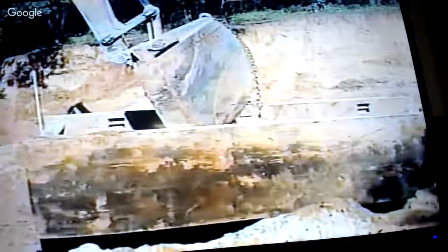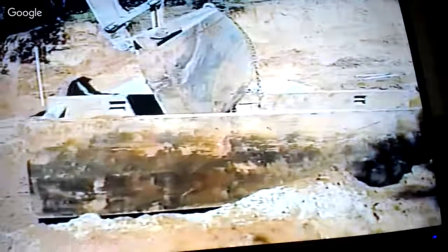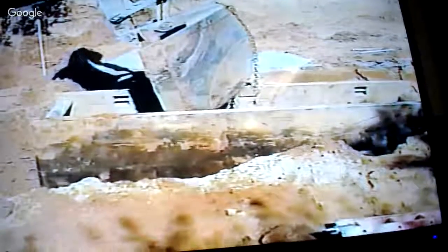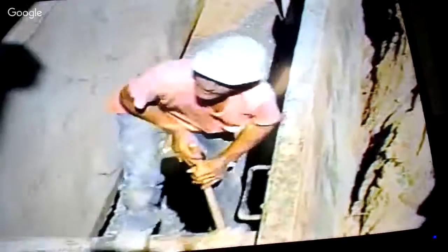When installing a shield, the guidelines listed by the manufacturer should always be followed. Overloading the system could lead to a cave-in. You should never be inside a shield when it is being installed, removed, or moved vertically. A protective barrier should be in place to guard you from falling materials when you are entering and exiting the shield.